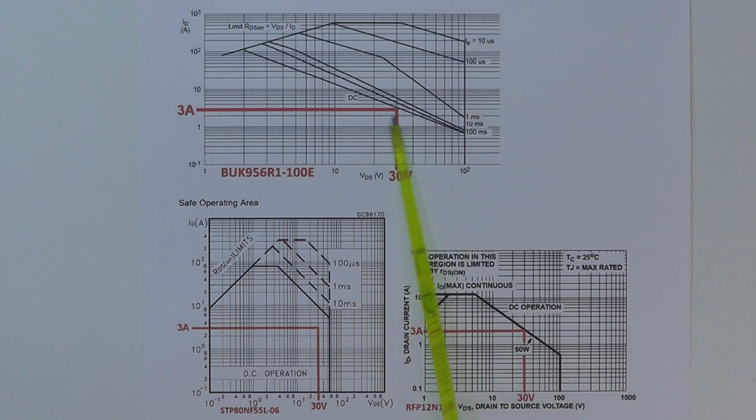So you have to derate that level, and in reality what you'll find is that when they're operating normally and getting hot, instead of 90 watts possible from the MOSFET, we probably get somewhere nearer 40 or 50 watts. But because we're using 4 power MOSFETs in our project, we've got some power sharing, so we're able to go up to around 200 watts maximum in this particular project.